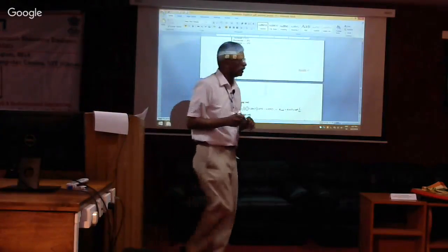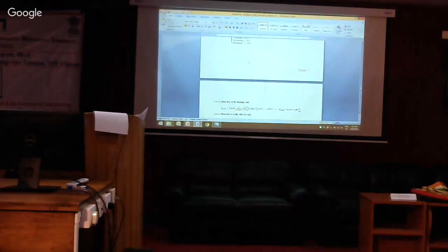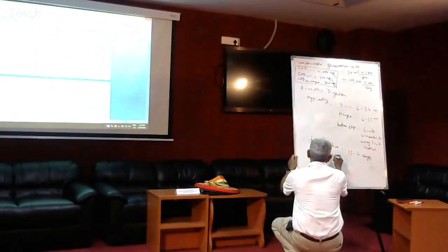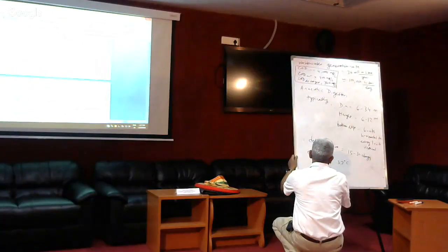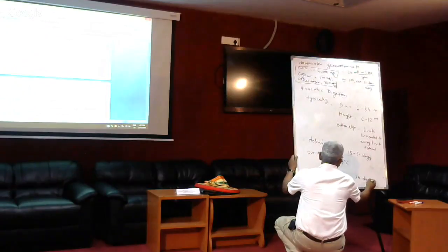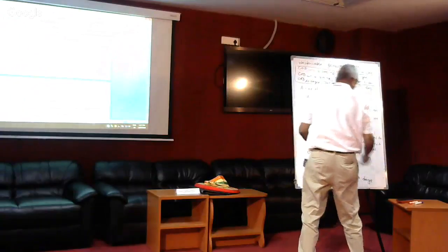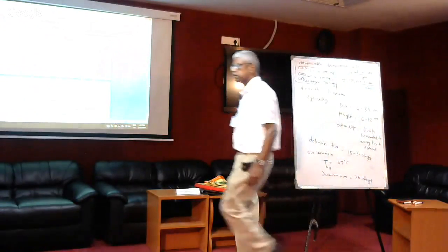So that's mesophilic. In our case, the digester runs at 37 degrees Celsius and detention time is 20 days. Okay. Questions?